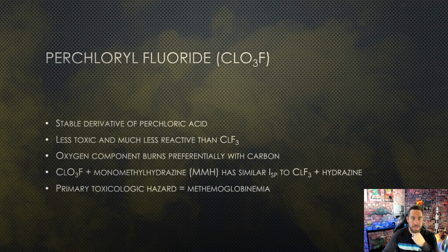In fact, so perchloryl fluoride plus monomethylhydrazine, which we'll talk about all the hydrazines in a little bit, but it's a really good hypergolic fuel. It has a really similar ISP to chlorine trifluoride plus hydrazine, which is a much more toxic combination. So you take this one, put it with MMH, and it makes a pretty good combination that overall has the same performance and it's a little bit safer than this other combination.